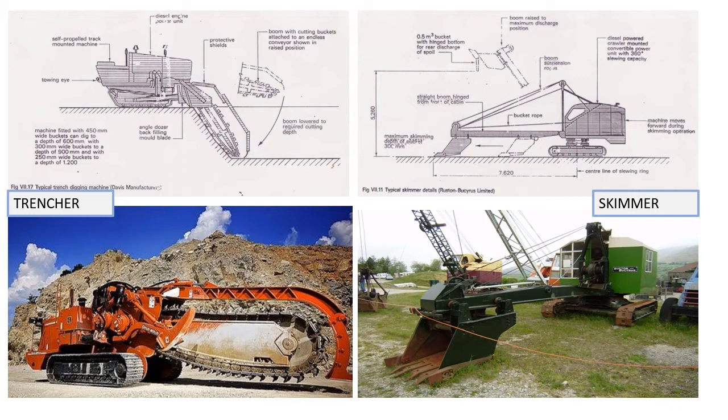The chain trencher is used for digging wider trenches, such as for telecommunication, electricity, drainage, water, gas, sanitation, and others, especially in the rural areas. The excavated materials can be removed by conveyor belt, reversible either on the right or on the left side of the trencher.